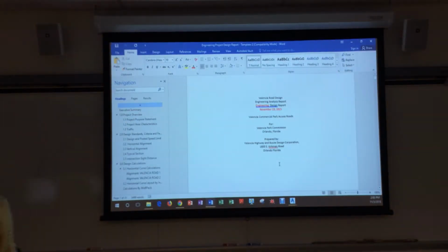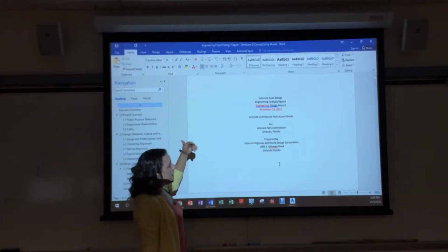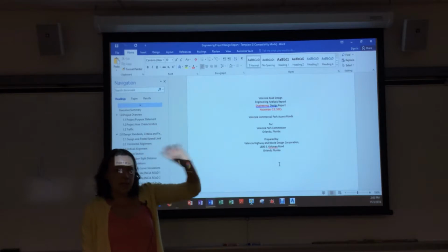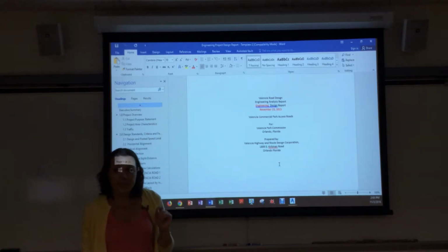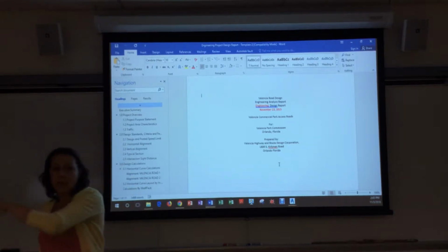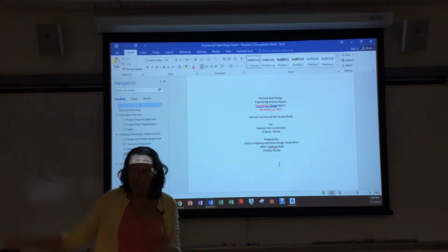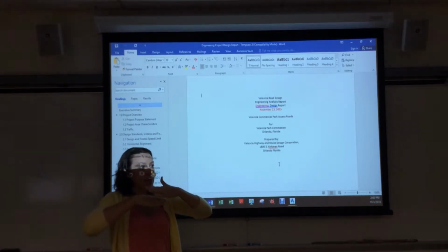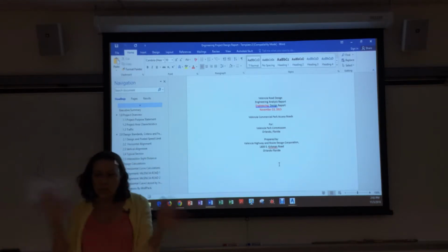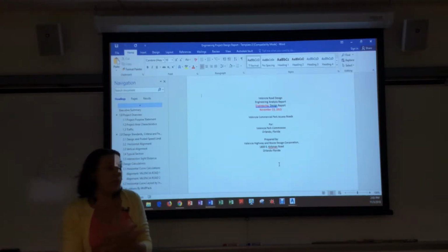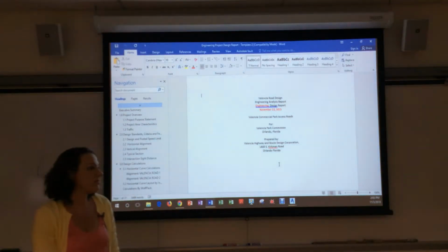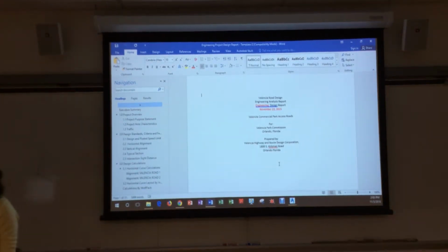Now, DOT, I've always done plan and profiles in subdivisions, okay? So the plan's on top, the profile's on the bottom. Sometimes you actually see DOT have plan in one sheet, and then the next bunch of sheets are profile. They don't actually put them together. I like them married up on the same sheet because you can see top to bottom. If not, then I'm having to look at two sheets more often than not. But it does happen, so don't be surprised when you get into a job that there's two different sheets. You'll be like, that's not what we did. Yeah, everybody has a different thing.